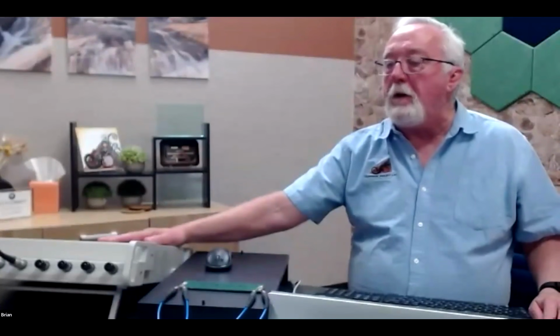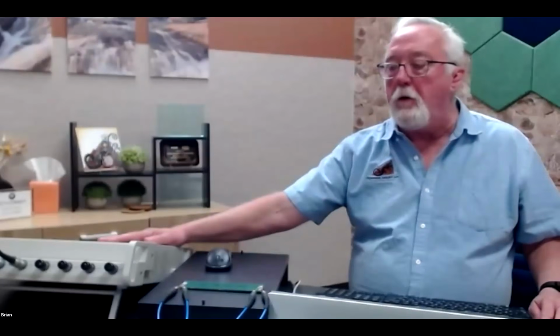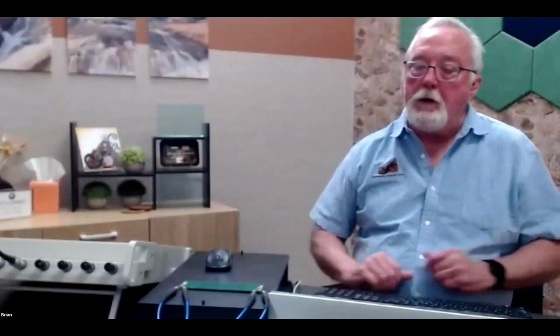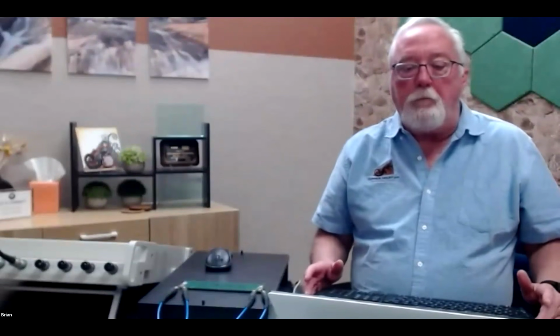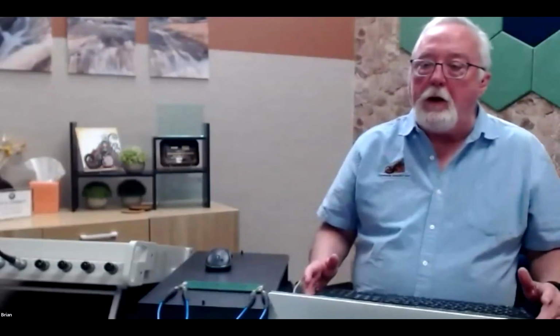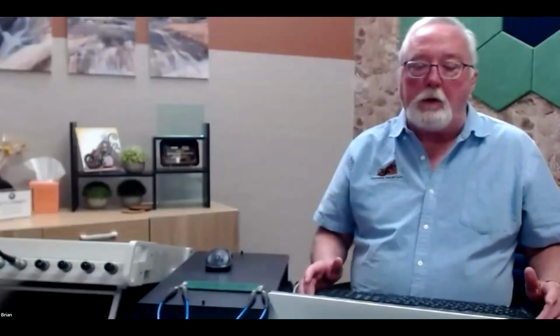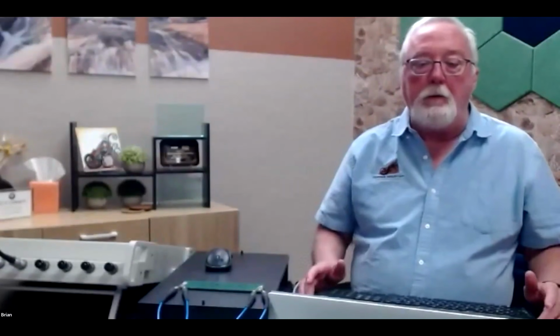It could be done, but there'd be a lot of fakery involved, because you'd really be measuring in the frequency domain, and then you'd have to put the harmonics together to generate a virtual square wave, and then plot that to create an eye diagram, and then add fake jitter. Really, at the end of the day, you're kind of better off using an actual digital setup to do that.